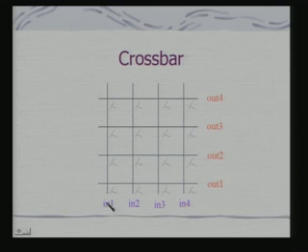So, here you see in 1, in 2, in 4 and out 1, out 2, out 4; these are input and output lines, and this is a cross switch actually. This switch can establish connection between any input point to any output point, and there can be multiple connections simultaneously being set up. So, if I put this switch on, effectively I get input 1 connected to output 2, and this input and output are basically the connection ports on the different processing elements. So, you can have any possible combination of input output.